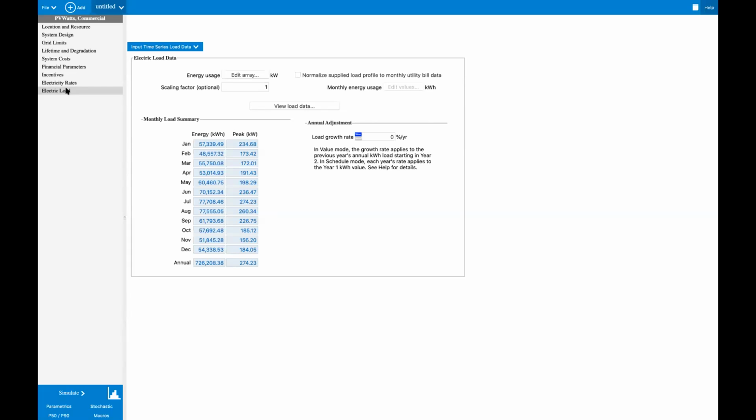If you're on a demand schedule that's estimating your monthly demand, in Ohio, most of our farms are on a 15-minute rolling window. Some of them are on a 30-minute rolling window, but it's looking at what is your largest demand spike over a 15-minute window in that billing period. So you may have great solar production during the day, but if ventilation fans and feed auger motors and well pumps kick on after the sun goes down, you're just going to move that demand occurrence to later in the day. And so it's important to understand your load profile if you have a demand rate.